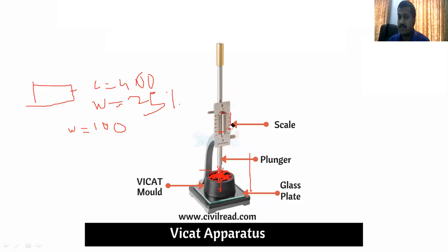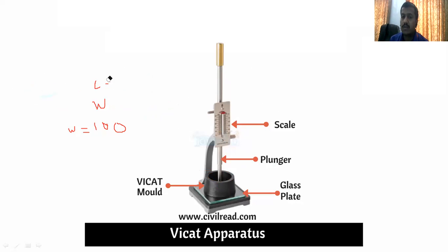Consistency is nothing but we have determined the exact amount of water which is required to make a good cement paste. So at 25%, if you are getting the answer, it is okay. But if you are not getting the answer at 25%, take the second trial. Increase the water content by 0.5, maybe 25.5%, or maybe 26% you can take.